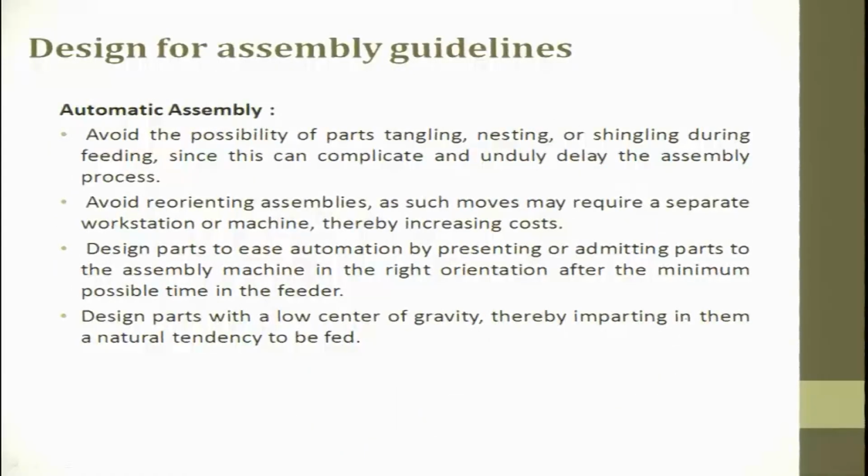The automatic assembly guidelines: avoid the possibility of part tangling, nesting and shingling during feeding. When you say automatic, you will always have a hopper, where you put all the parts, and then you will have a feeder, and then you get one piece at a time, whatever it is. Okay, one piece you get.